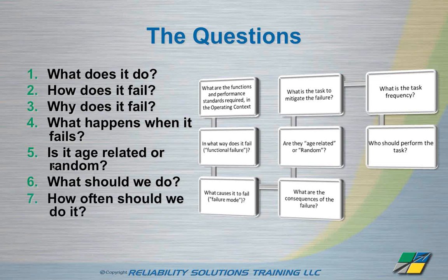How often should we do it? This is another question that people often struggle with. And really, when we talk about how often the task should be done, the mistake a lot of people make is they base the frequency of the task upon the criticality of the machine. I hear this all the time. Oh yeah, we do vibe readings once a month on these machines, but these two over here are really critical, so we do vibe readings once a week.